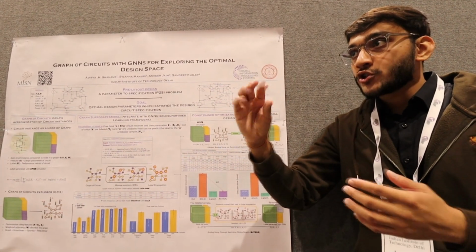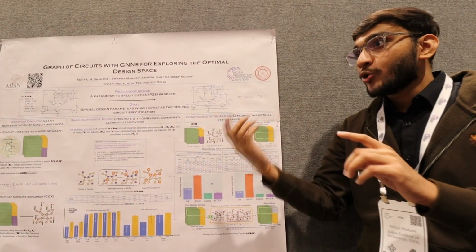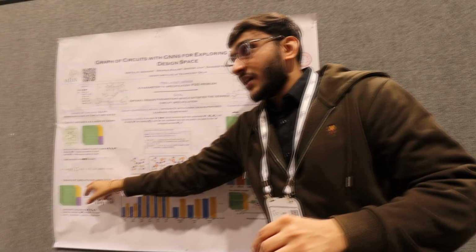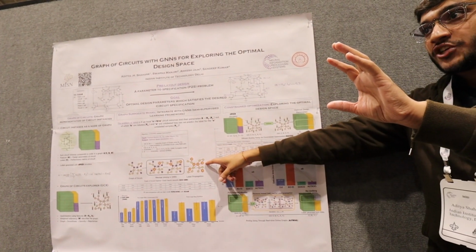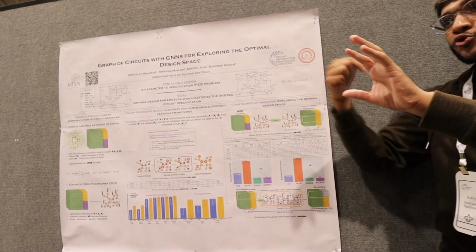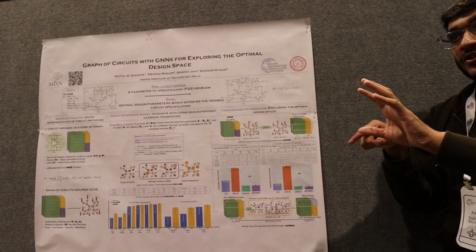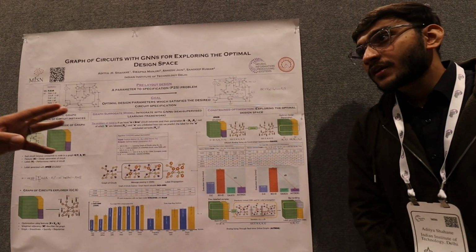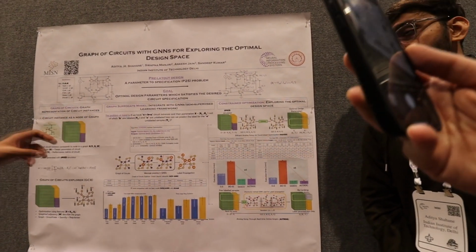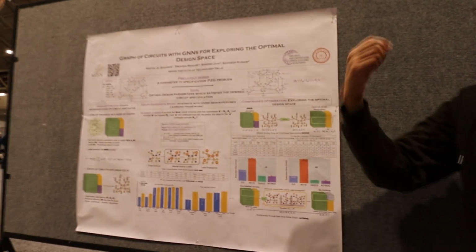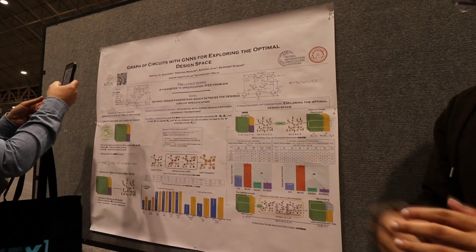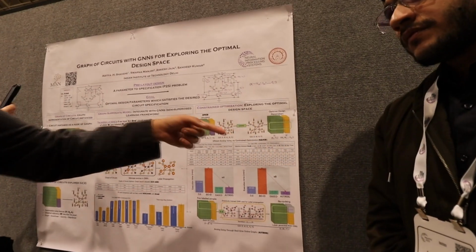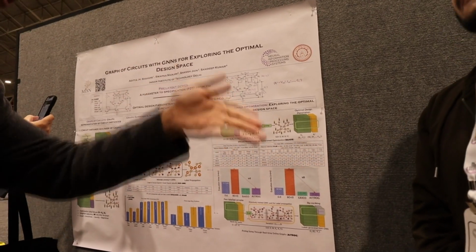But those solutions will not have labels, correct? How do you get the labels? This problem again becomes something like this, where you have some labels, most of them unlabeled. But you have already trained your GNN. So that graph surrogate model will be used to put the labels corresponding to those new solutions. Solution, I guess you mean a design. Yes, design. The labels like the gain, UGB, those are my solutions. So basically, the GNN output will be a bunch of labels, or you call it a solution.